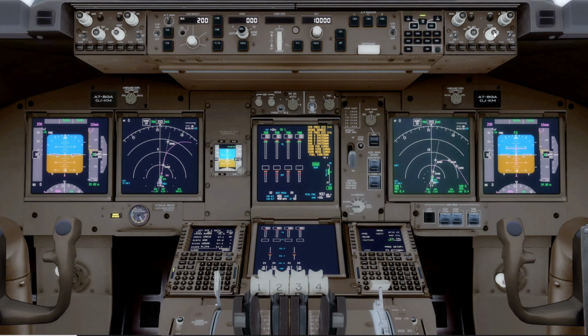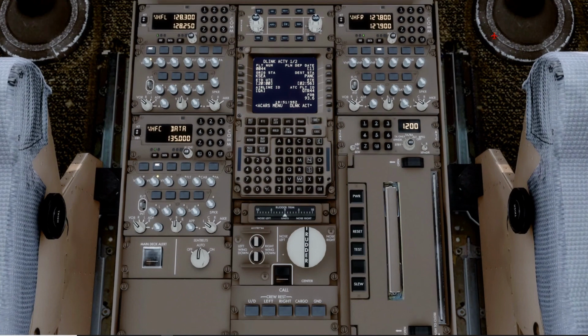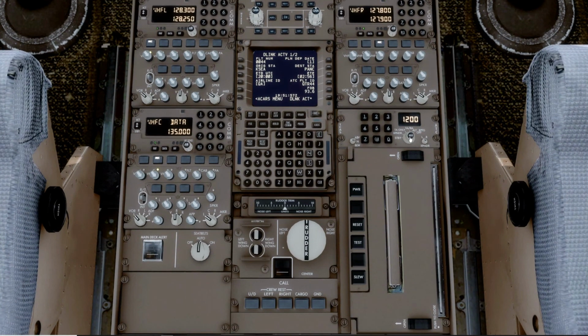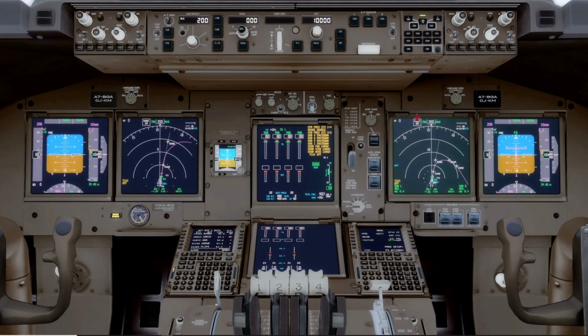TCAS off displayed. We can go down and see if the TCAS is on now. And it probably is, so we don't want that on. I'm going to go to standby, and then we should see TCAS off displayed. As long as the IRUs are in nav, which they are already, then this TCAS off will be displayed.